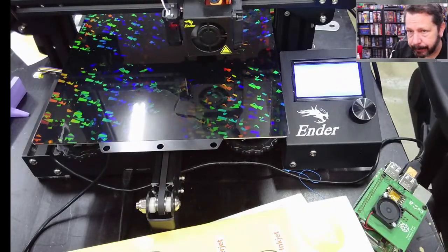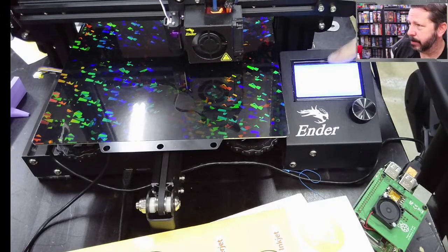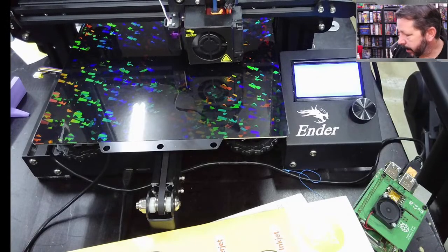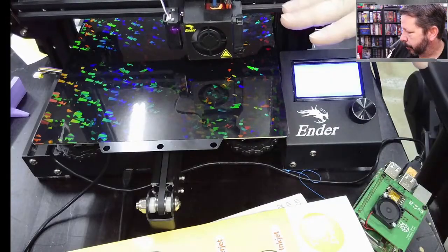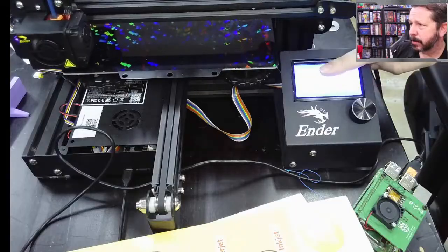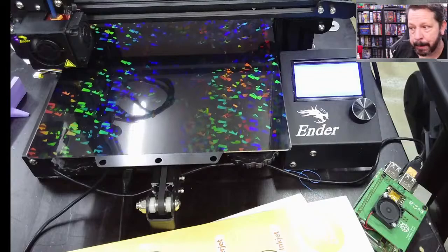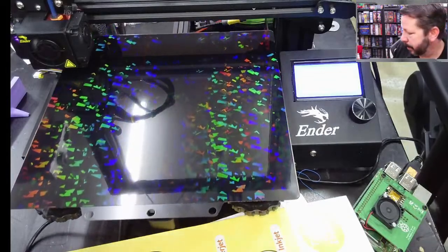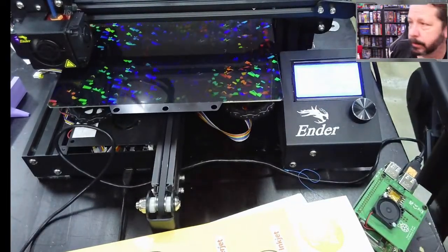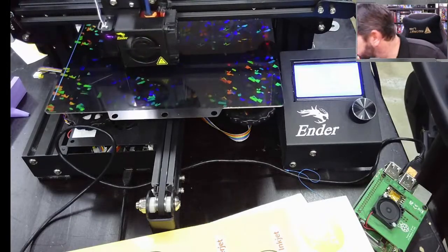On this Z offset, there is also a similar command in plain Marlin that you can use on your screen here. If you have it enabled and you're printing, you can double click this knob and it will go to a tuning menu, and there's an option called baby stepping. And baby stepping is the same thing. You turn the knob and it will drop the nozzle down or raise it up, whichever way you're going. And it does the same thing.